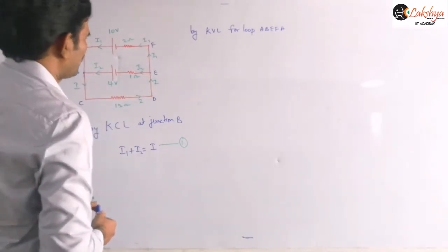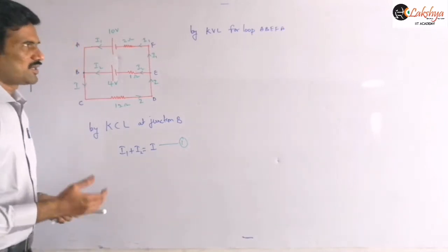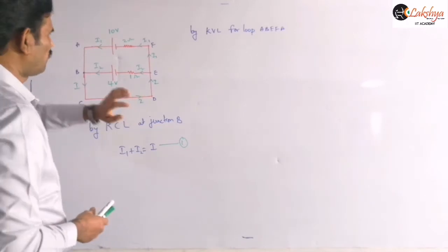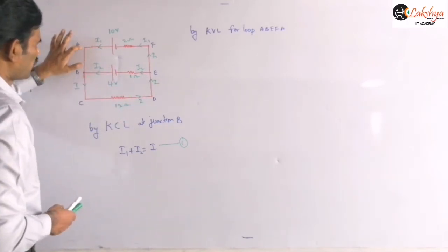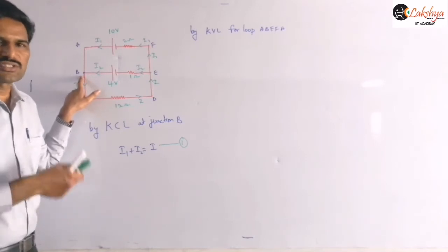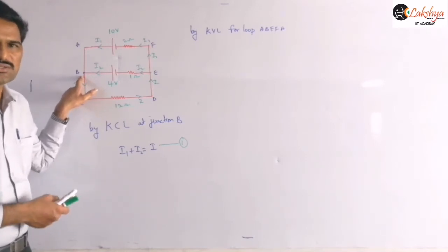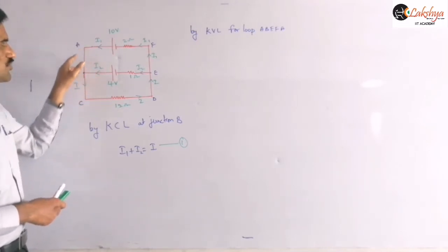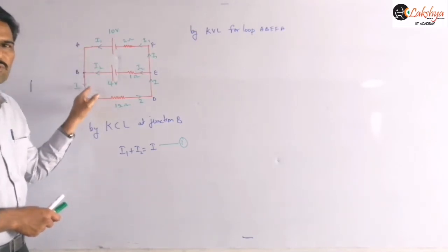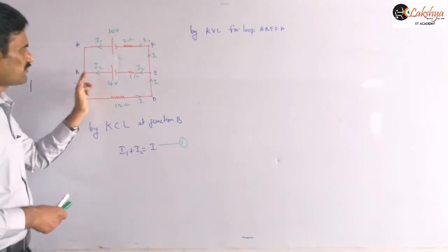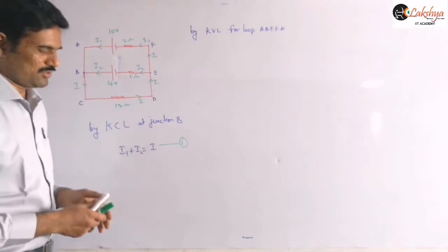And so now let us write this Kirchhoff law here. We need to apply our sign convention by following that path from A to B. So from A to B, is there any element? Element means like resistance or cell or capacitor. Is there any such device? No device is there. That means this is a conducting wire you may consider here, so there is no potential drop when you are traveling from A to B. Got it? Next, when you are traveling from B to E, along this direction.